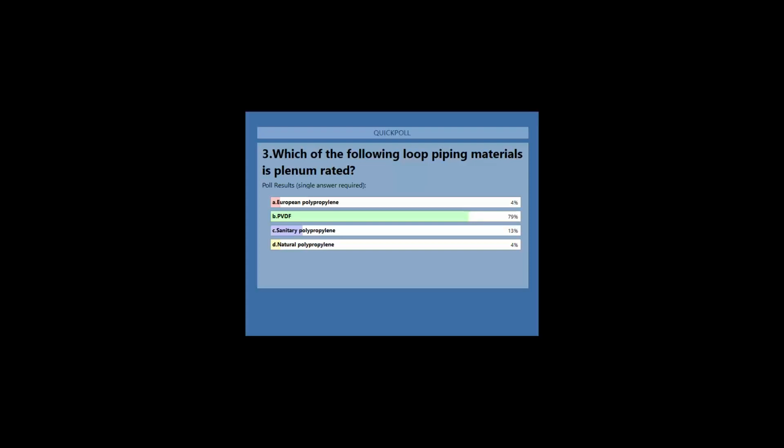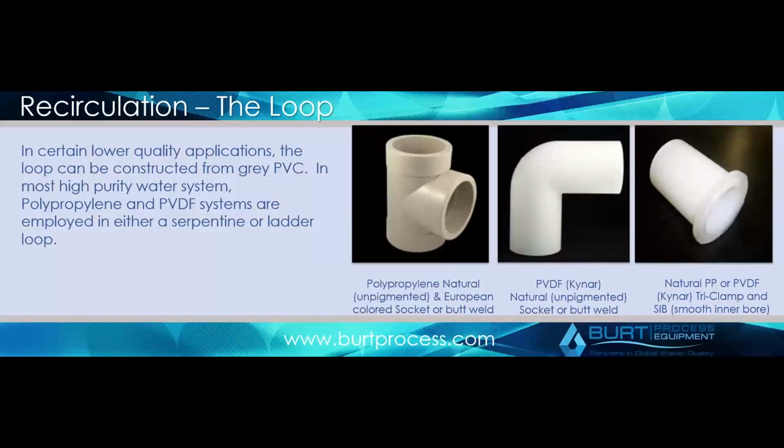Of course. Yeah, so I mentioned a couple times sanitization. I mentioned bacteria in the system. Anytime you have a water source, even when you have a recirculation running in your actual system, in your loop, it's still an area where, and you can even see looking at some of these different pipes, there is going to be some kind of roughness within that pipe. And regardless of the velocity you choose, even though you do want to maintain a turbulent velocity through your loop, you do run the risk of bacterial buildup in your system. Now, you're not talking about a large amount of bacterial buildup, but enough that it will affect your overall water quality. And that's really the determining factor in when you want to sanitize.